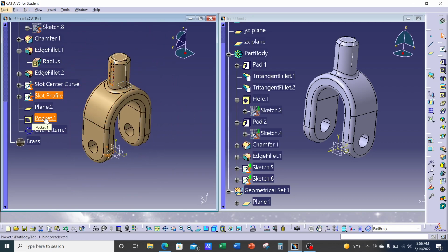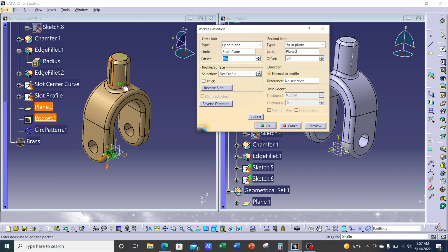And it's going to use the pocket command to create that groove. We can also actually use the slot command. Okay, so let me deviate slightly. I actually don't know if this was meant to use the slot command, but in this case, either one will work. Typically, you want to use slot on curved paths. A good example is threads on a bolt or a nut. Here, because it's a straight shot or linear path, a pocket will work.